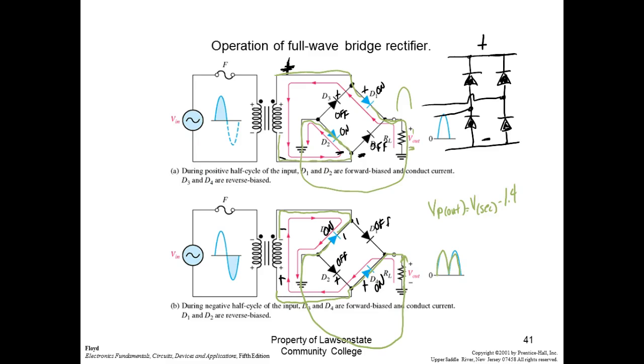No, it's regulated. Now your phone chargers, these are regulated. So if you look at the back of these, this is going to give you a voltage, and you can pretty much hook that up to a resistor, and you can run. It's going to be that voltage as long as you don't exceed the current rating of the transformer. These cannot use unregulated power supplies. They have to use regulated power supplies because what they're doing is so critical. They can't have that voltage vary with the load.